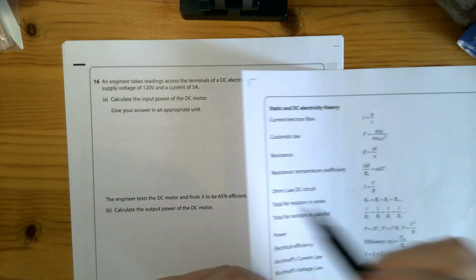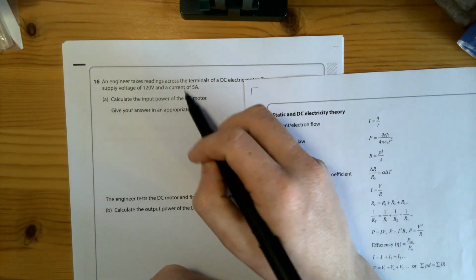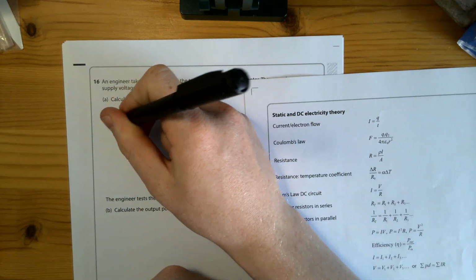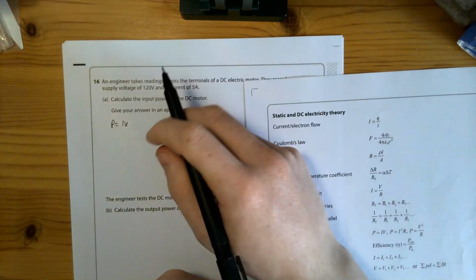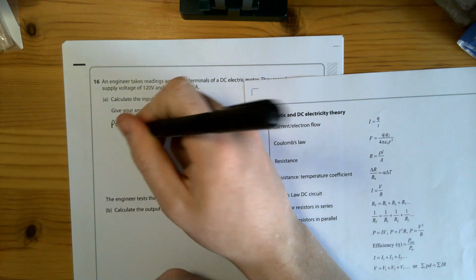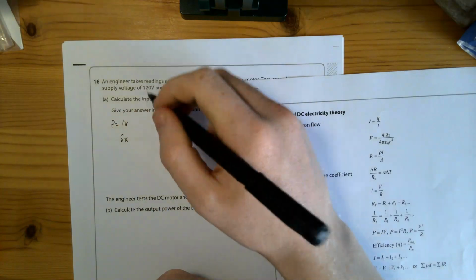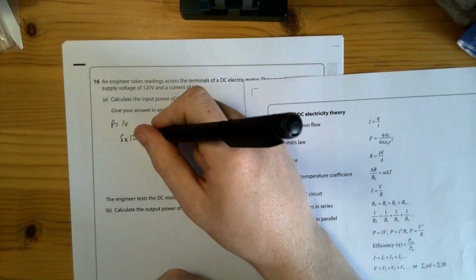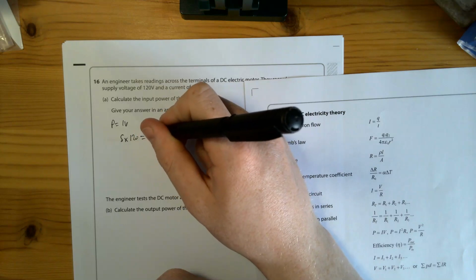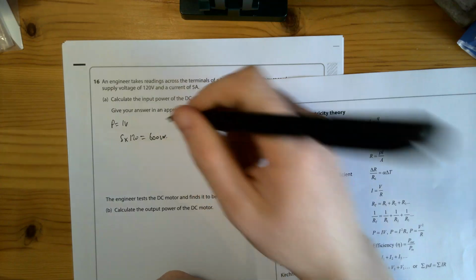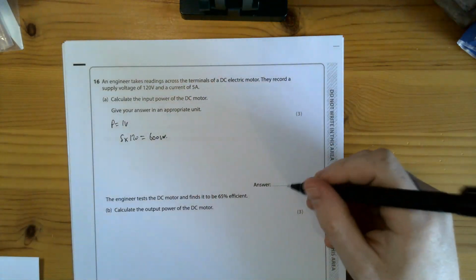That's what I'm going to use because I know that I've got an I, which is a current, and I'm going to have a V, which is a voltage. So writing down P equals IV. I've got a current of 5 times by a voltage of 120. Therefore, I'm going to have a power equivalent to 600 watts. So my answer is going to be 600